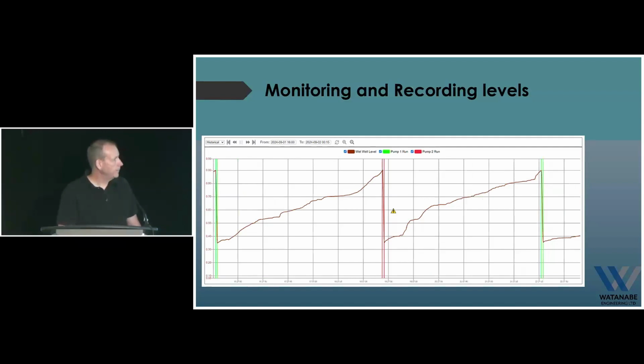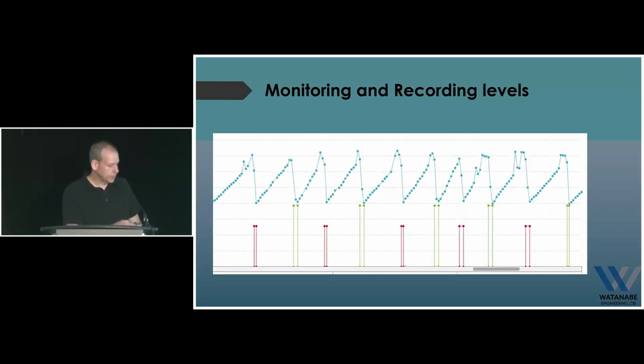So this is kind of a happy pump system. We've got pump number 1, pump number 2, and we can see that the actual pump cycle is pretty much the same for the 2 pumps here. So, steady incline, same sort of decline for both pumps. But then if we look at this station, this one is straight away telling me that we've got some sort of issue with one of our pumps. We notice that the red pump here has got a short cycle time, and then the green one's got a longer cycle time. So this could probably be due to some ragging in the pump.